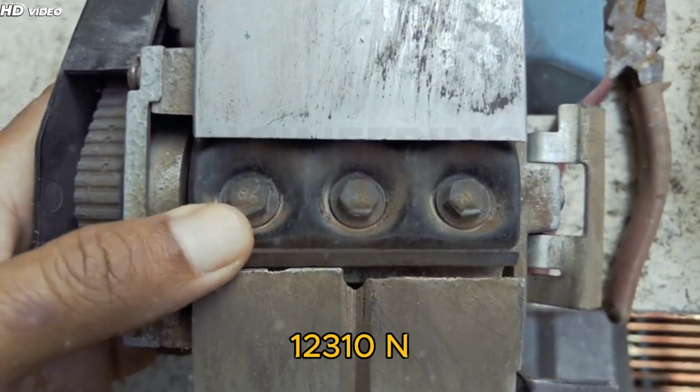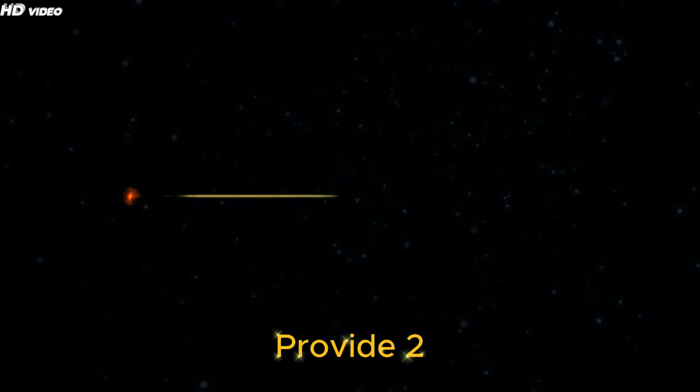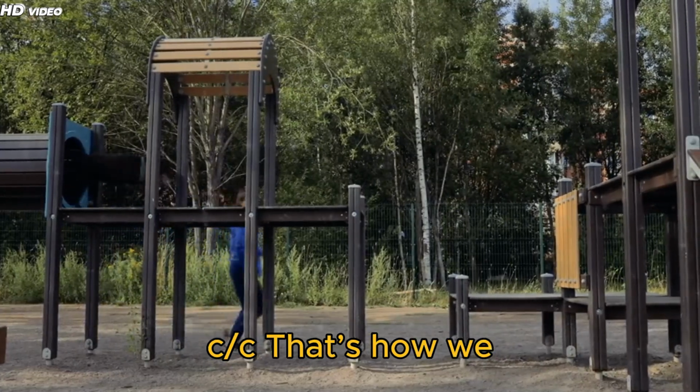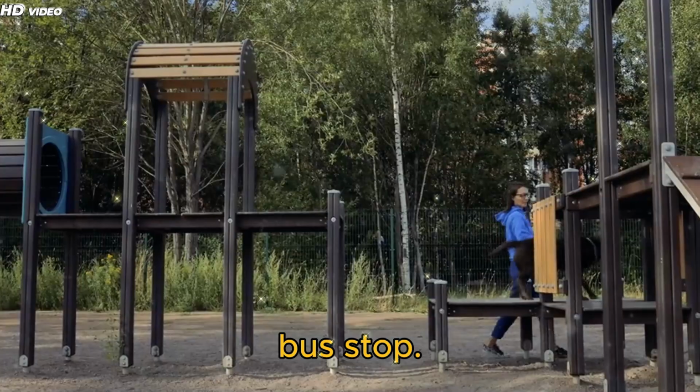Net shear force SF to be resisted is very small. Provide two-legged 8 millimeter stirrups at 200 millimeters c/c. That's how we design a cantilever shed for a modern bus stop.